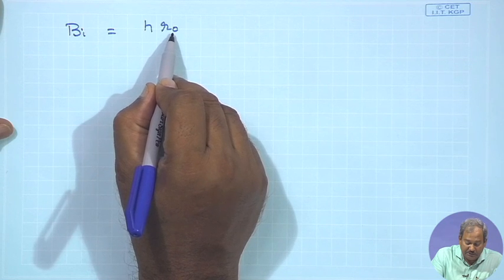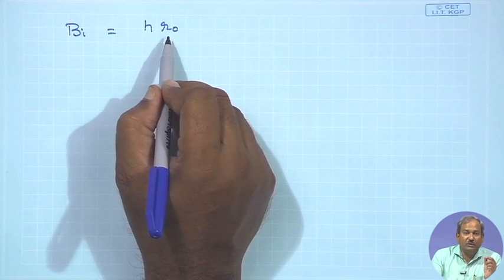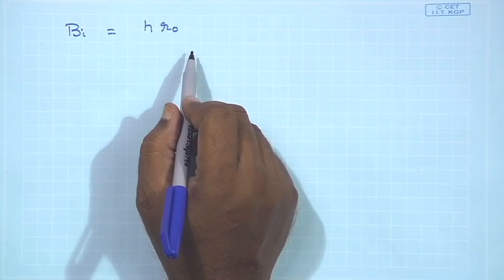in temperature. Obviously, when a thin wire is placed in an oil bath, the maximum temperature is going to be at the center line of the wire, and as we go towards the periphery, the temperature will decrease, and right at the periphery of the solid cylindrical wire, the temperature is going to be the least before it starts convection to the cold oil bath.